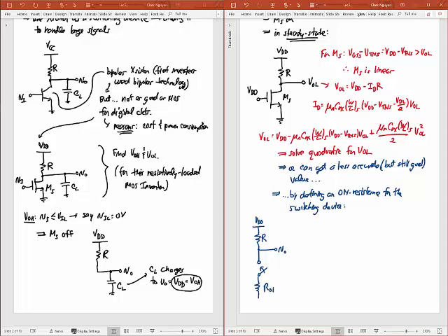But then from here, I'm basically, when I turn on the transistor, switching into what I'll call an on resistance associated with that transistor. So I have an R on there at the bottom there, and I'm going to have some input voltage V sub I that then controls whether that switch is on or off. Okay, so in this case that I'm looking at, I have a high V sub I. It's closed that switch. So in effect, what I have is a voltage divider circuit there. Okay? And so all I really need to know now, once I switch this in, is what is the value of this resistor R on, right?